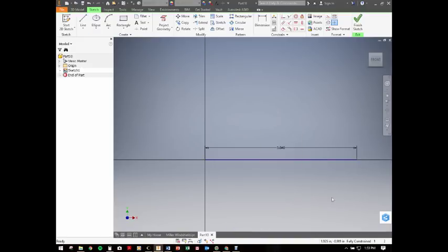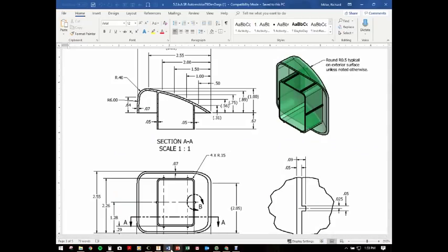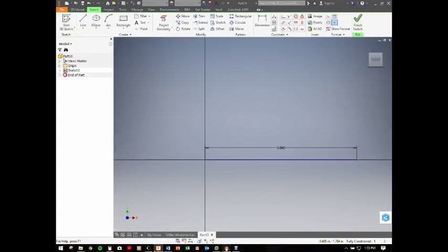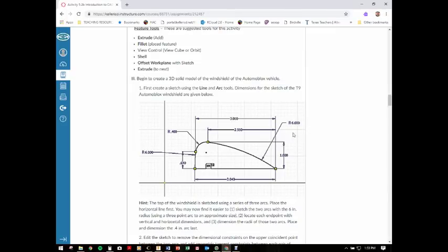And I don't want to make a contiguous line going up in here. In fact, these are just going to be construction lines in here. This is a series of arcs here. These are arcs, and you can see where the radius is. This is a radius of 6. This is a radius of 0.4 here, and this is a radius of 6 here. So all I really want to use are some construction lines to identify these endpoints in here. So this is up 1 and over 2.55.